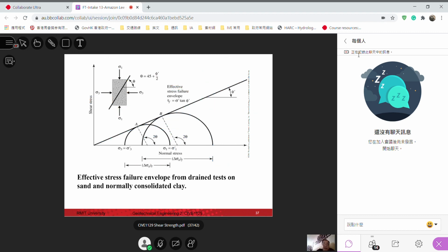So now we want to do another one, the third specimen, a similar soil. From each layer of the soil in the site investigation, we take out a column of soil specimen. From that, we trim at least 3 specimens for conducting at least 3 triaxial tests.